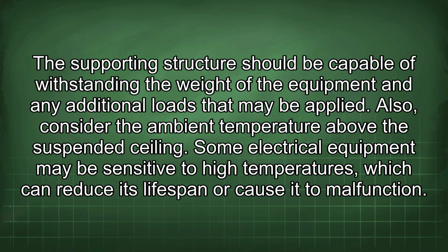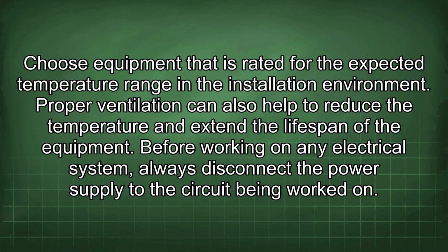The supporting structure should be capable of withstanding the weight of the equipment and any additional loads that may be applied. Also, consider the ambient temperature above the suspended ceiling. Some electrical equipment may be sensitive to high temperatures, which can reduce its lifespan or cause it to malfunction. Choose equipment that is rated for the expected temperature range in the installation environment. Proper ventilation can also help to reduce the temperature and extend the lifespan of the equipment.